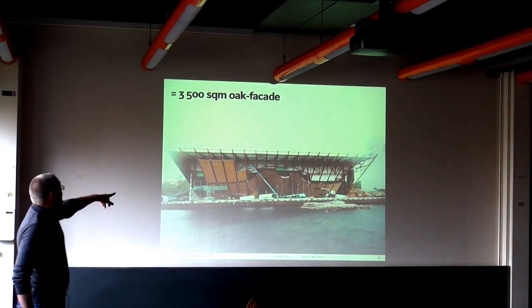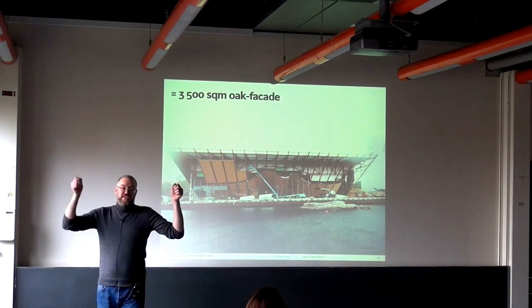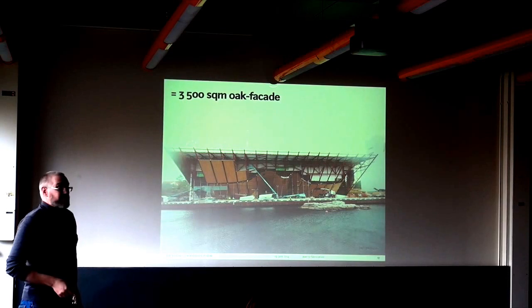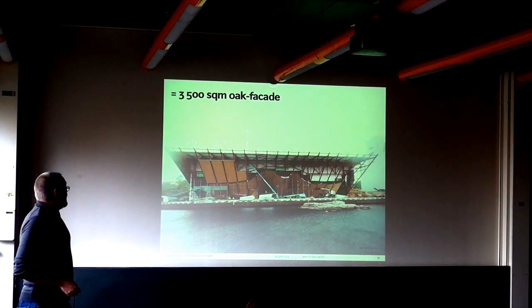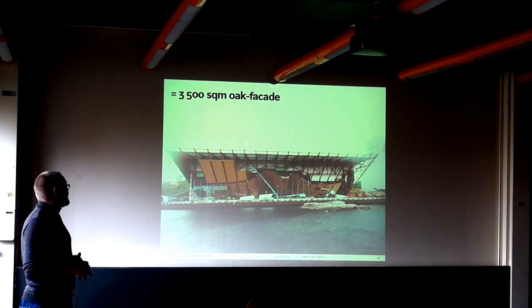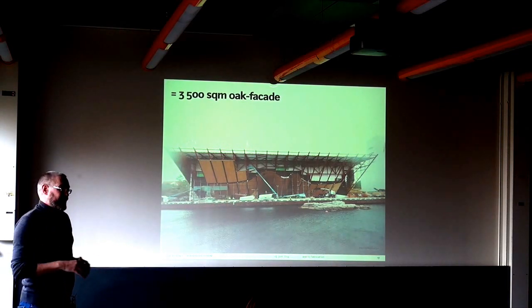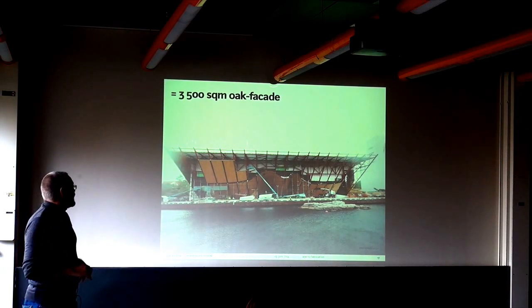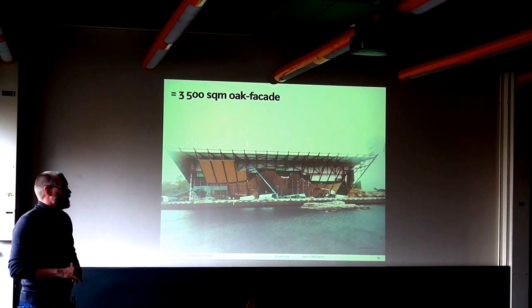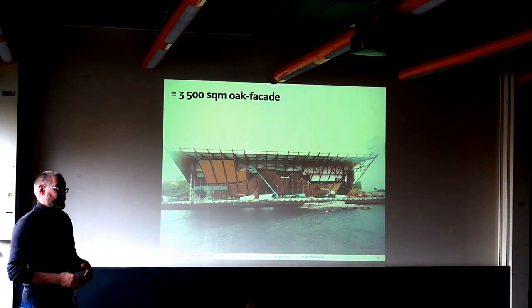The black gaps here are where a few cladding boards are still missing, so that you can still reach the tightening points where the elements are fixed to the steel structure. So the steel structure is planar? The steel structure is not planar, but those are straight I-beams going down at the right angle. So it follows the geometry of the facade. The trick is really to have straight lines going down the facade everywhere.